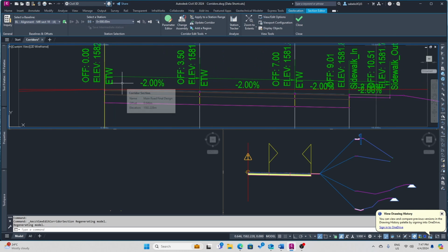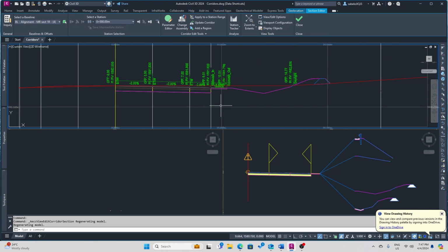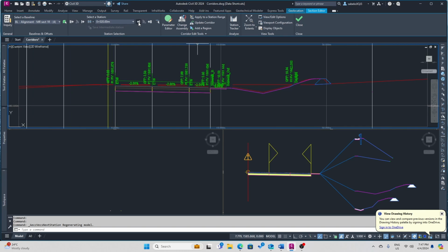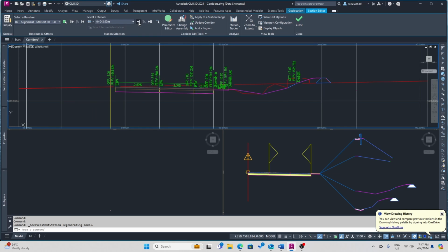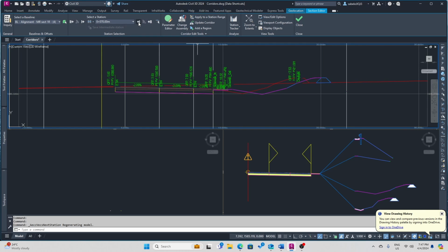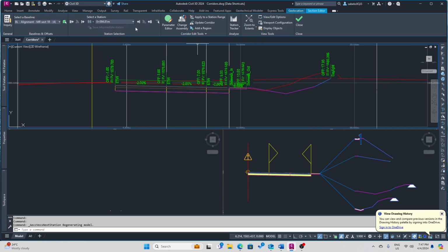Now we can see that yes, our corridor seems to be modeling nicely. Yes, it's working quite nicely. And it's beginning to move away from the center as we get the median. So what we're now gonna do, we're gonna put in a curb right in here just to mark the median. Okay, so we will just further do developments on our assembly.